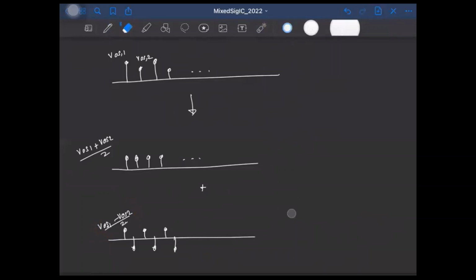So what I have done here is essentially decomposing the signal in terms of its Fourier series coefficients, right? Since it has a period of 2 samples, you have only 2 frequency components, right? So the period is 2. So you have the fundamental as 2 pi by 2, right? So you have only 0 and pi. The frequency components it can have are k times this. K equal to 0 corresponds to DC, that gives this. And k equal to 1 corresponds to a frequency of pi.